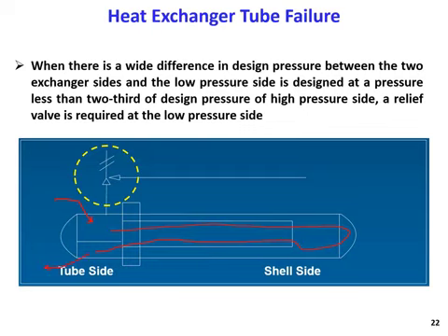Okay, so this is my tube side, and I also have, let me pick another color, the shell side, which is usually from here, and it goes all the way through the shell, and it will leave from this part. So this is countercurrent, and we usually operate at countercurrent.